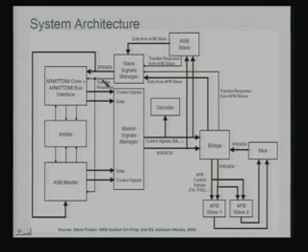This is a transfer response: what is the response to the transfer transaction which is currently being executed? And this is the data which flows from the slave back to the master. This is where the arbiter is. Once the request comes in, the arbiter resolves and gives a grant to the core. Only once it gets a grant is the transaction initiated.